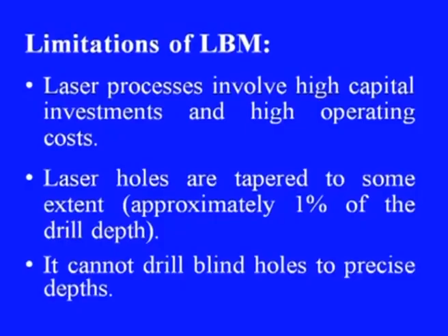Now, let us look into some of the limitations of this process. Laser processes involve high capital investments and high operating costs. Laser holes are tapered to some extent, approximately 1% of the drill depth. This can be explained like this.